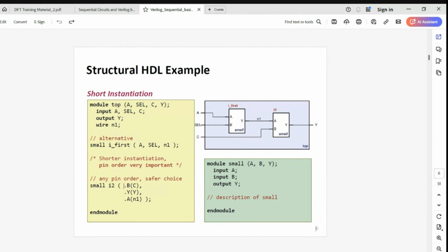This is important, guys. This is important because though you will not be writing an RTL code, okay, you will work with the design netlists or RTLs coming into the DFT team from the RTL team. You have to sometimes open the code and see if something is fishy, or you want to trace some module, you want to trace some pin. Okay, let's say from A to this A, you want to trace it in the RTL instead of schematic. That is also a skill. We will learn it. I'll show you when the lab starts.